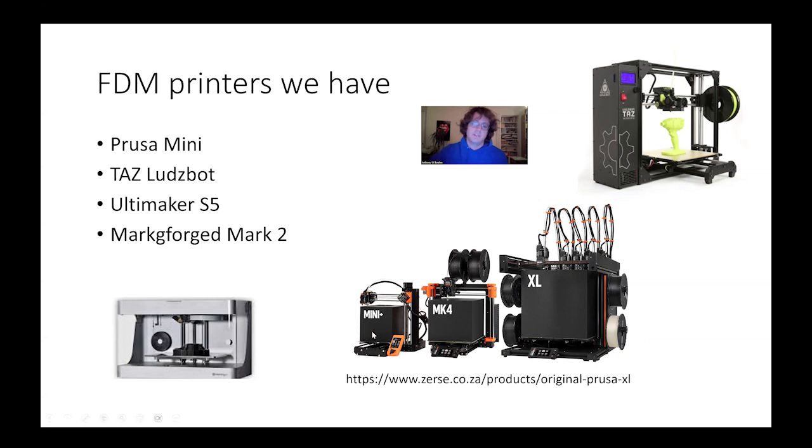There are a couple of different nuances in the technology. As you can see, the Mini here, as well as the Lulzbot Taz up here, are both what they call bed slingers, which means the y-axis is on the bed travel, and the x-axis is on the gantry above, as is the z. So x and z mean the nozzle is moving, but the y-axis means the bed is moving. There are some disadvantages to that. It can be a little bit cheaper to make that configuration. But it could also lead to some wobbling issues because the bed is what's moving and that's where your part is. And so if your part is not completely fixed, then that can lead to some issues.